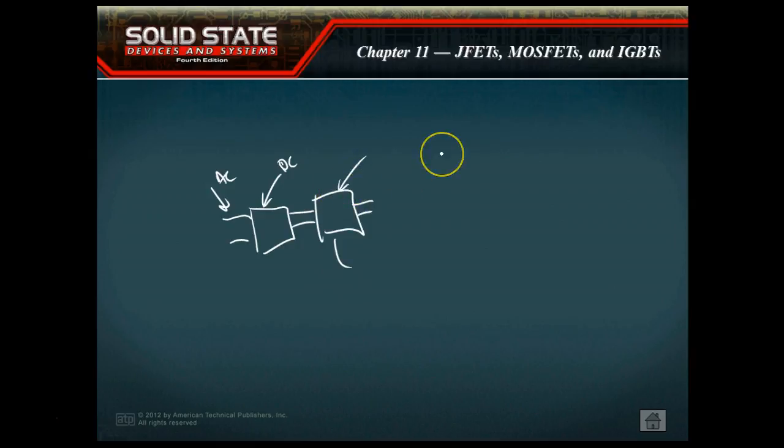But now I'm controlling this electronically. The problem with using just bipolar transistors operating in the linear region is that motors are going to try to pull a lot of current. If we operate the transistor in the linear region, it acts like a rheostat. So the more voltage it drops, and we're pulling a lot of current, it's going to cause the heat to go up real high. So what we want to do is operate these things as a switch.